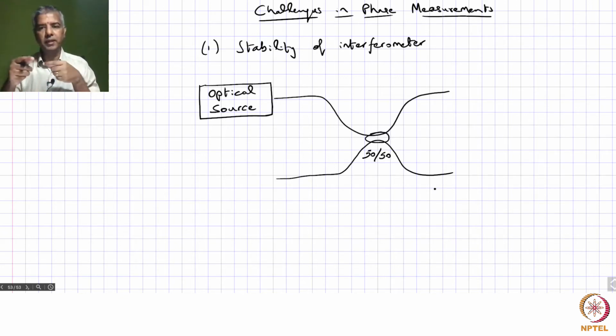But if you get your interaction length right, you can achieve the kind of split ratio that you are interested in. Those are commonly available in fiber form, what is called a fused biconical taper coupler. So let's say we have one of these couplers and we can split it into two.